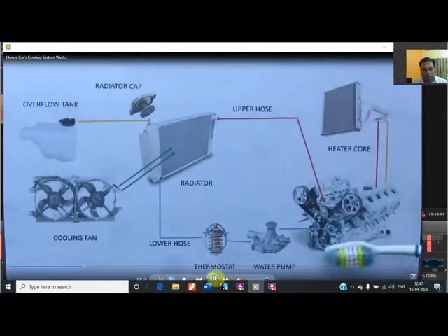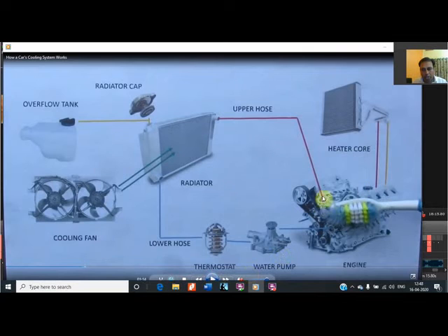This is being shown. In the video you can see that although the major quantity of hot coolant is going to the radiator, a certain quantity is bypassed to the heater core. The heater core is shown, and this small radiator with a blower, because the blower is used for heating the passenger cabin, and the hot coolant after going becomes cool, and the cool coolant goes to the engine block again, and after taking the heat the system runs again and again.